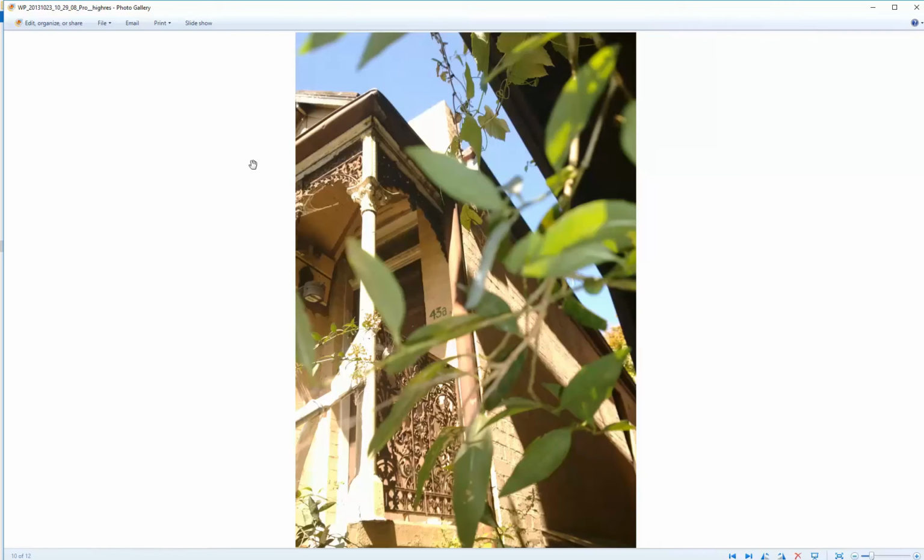Yeah, so that'd need a valley. That'd have a valley gutter between the wall and the roof. So that's a different type of gutter. It's a concealed gutter basically that's done mostly with flashing type materials. To the front. Yeah, so that's maybe why they brought this across, because they didn't want to put a downpipe on the other side. But yeah, you'd have a downpipe on the other side.